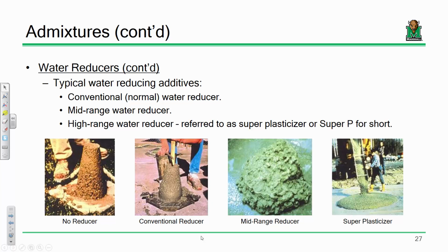So once you remove the cone, the concrete slumps. The easiest way to actually measure that slump is to take the cone, turn it upside down, set it down right next to it, and you can see this metal bar. That's the rod that was used to rod it 25 times. You lay that flat, and then you can use a tape measure to just, from the center of that cone, measure how far it goes down. We typically measure to the quarter inch.